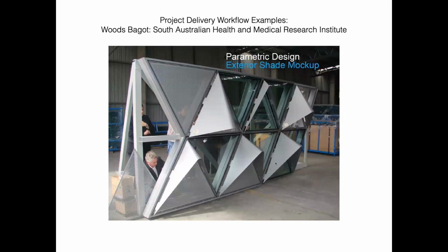When you're doing a custom curtain wall, they actually mock these things up at full scale. And then it's really interesting. I don't know if you've ever seen this or not. If you haven't, get onto YouTube sometime in your free time and look up curtain wall testing. What they do is they get a jet engine, and they blow incredible winds, lateral loads at this thing, while also throwing water at it, right? And trying to make sure that structurally it's going to withstand wind loads of a certain strength, and also that it's sealed and it's not going to let moisture in. So it's a pretty incredible process.